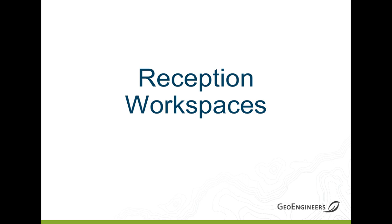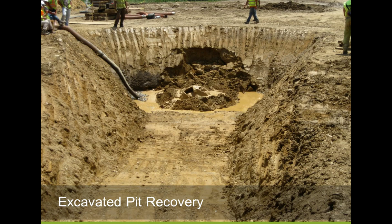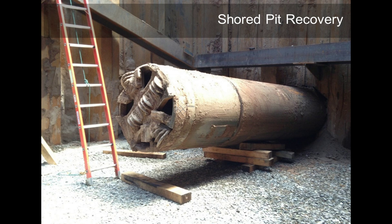So we looked at the launch workspaces and kind of got a sense for what's required there in terms of space and what equipment is there. One of the advantages of direct pipe is the relatively limited workspace and equipment that's required at exit, typically. And we'll look at a couple of examples where a little bit more work was required at exit, but typically it's relatively limited. It can range from just digging a shallow pit and waiting for the machine to show up to a shored pit recovery, similar to what you might see in a microtunnel.